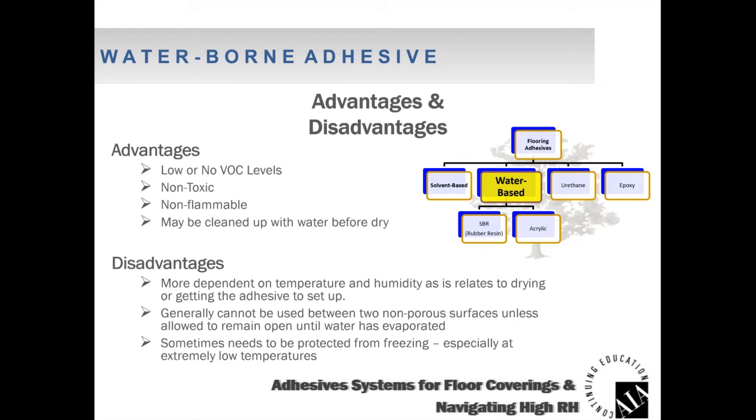Some of the disadvantages out there: more dependent on temperature and humidity because you're dealing with water here. So in cooler environments and low airflow, it's harder for the water to evaporate, so it takes the adhesive a little bit longer to set up.